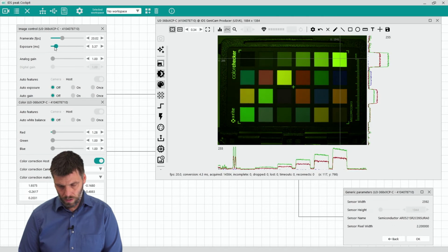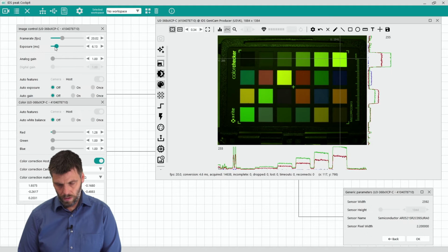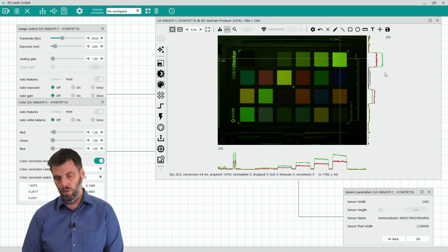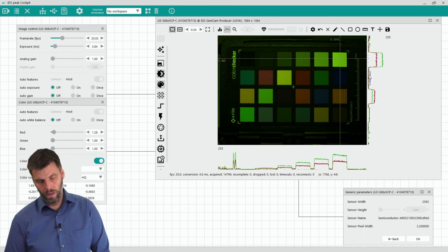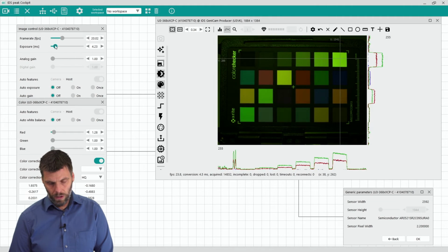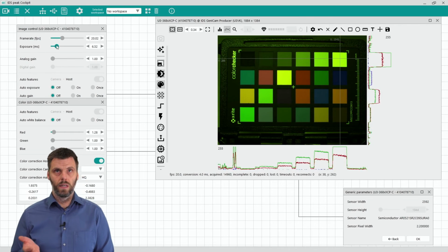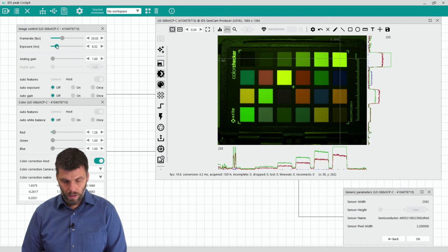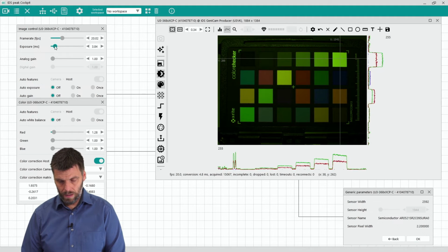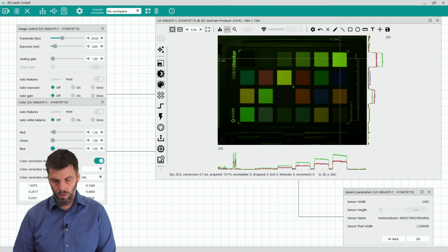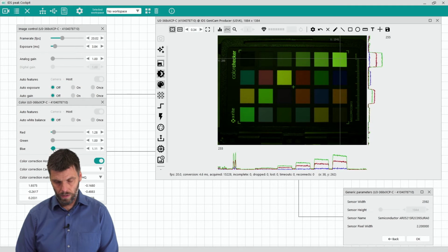still an overexposed image. So we reduce the exposure time to a point where we also get valid information in the green area. If you don't see it, I will increase it. So you see we have here a line. Green is way overexposed, so we bring it to a valid value, and then we see, okay, blue is completely missing in the image, so we increase blue so that it reaches the green.